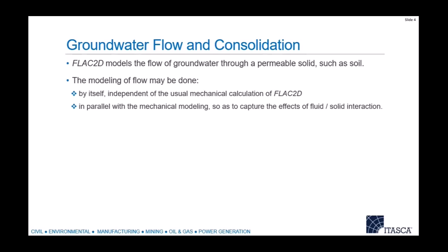You get to pick which one is important, and it's also important to be aware of the relative timescales of these interactions, right? The mechanical response versus the fluid response, because that affects how you set up the model. If one's happening much faster than the other, as is pretty common, there's no reason to do a fully coupled analysis. You can separate those things in time and do them separately, and it's much more numerically efficient, okay?